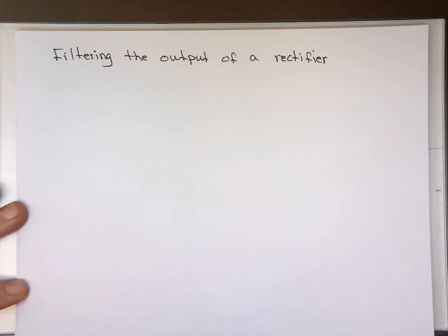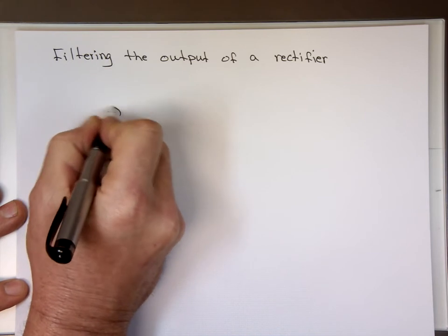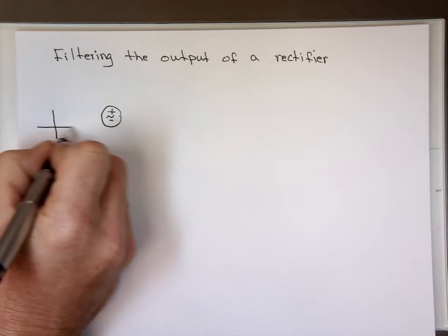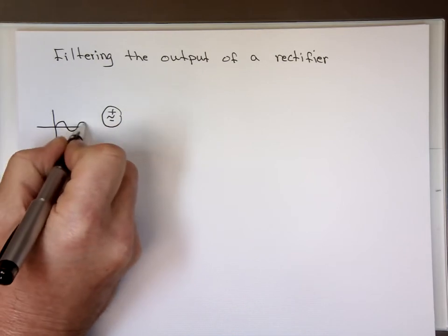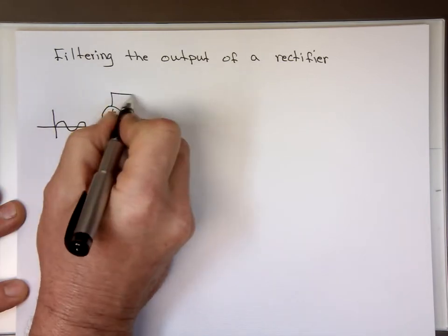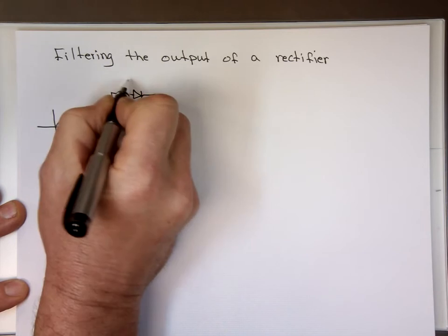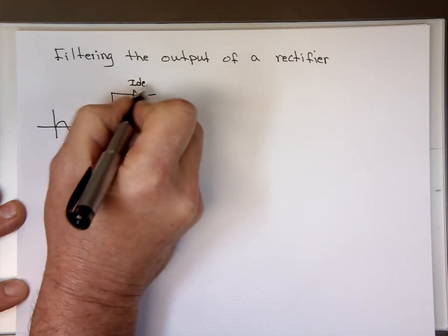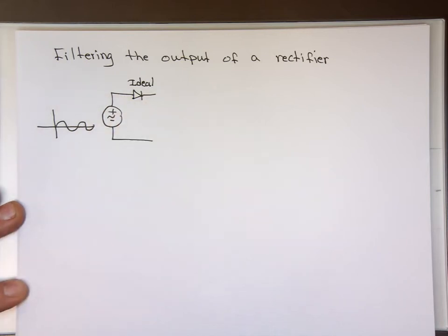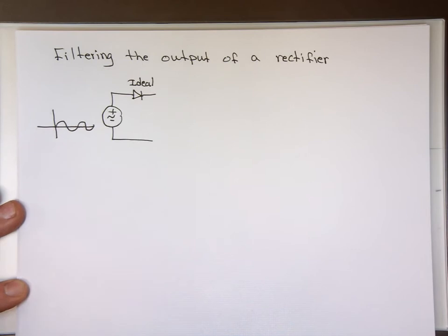So now let's take a circuit like this one, attach a sine wave here, put a diode there. Let's say ideal diode. Ideal means you only need a hair over zero for the current to flow in that direction. So once this is conducting current, we'll replace it with the short circuit.